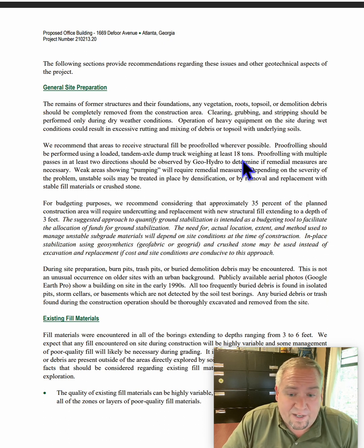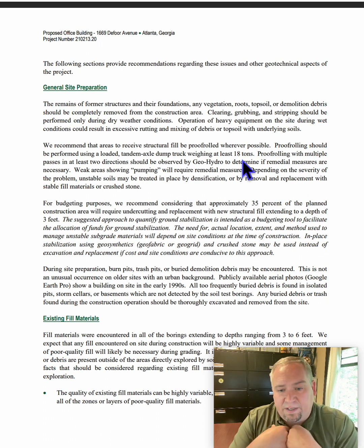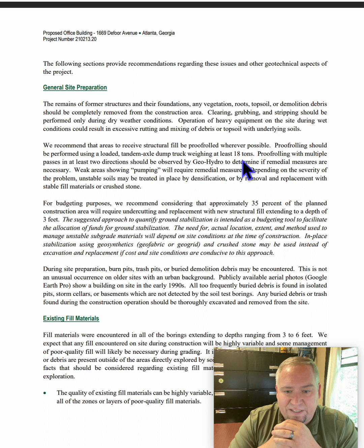And proof rolls are also done at the final stage too, and along the way. Whenever you're doing proof rolls, just know the geotech has to initiate and tell the driver they're in full control of the driver. Now, we as a company, we understand everybody's looking at back tires and not at being visually aware of the area. So we want to actually have a safety meeting before we do a proof roll. Who's directing the driver? What areas are we planning to proof roll? We shut down those areas, and we stay on high alert, because everybody's micro focused, but they're not always macro focused.